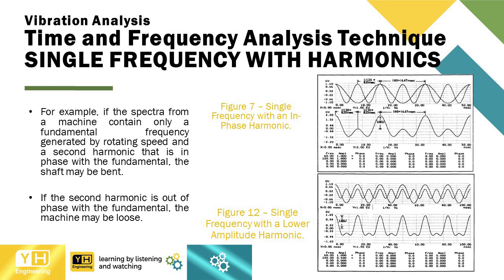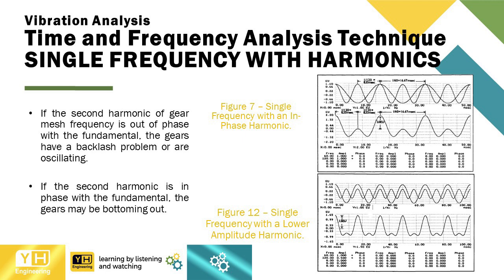If the second harmonic is out of phase with the fundamental, the machine may be loose. If the second harmonic of gear mesh frequency is out of phase with the fundamental, the gears have a backlash problem or are oscillating. If the second harmonic is in phase with the fundamental, the gears may be bottoming out.